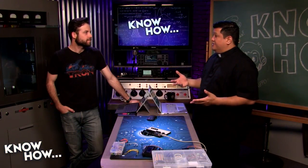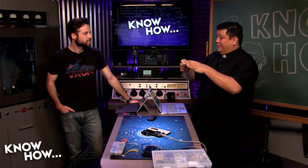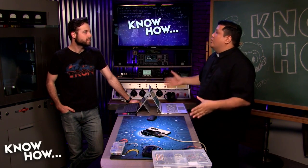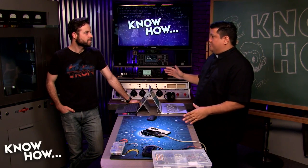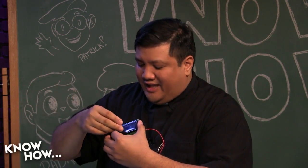They get washed out a bit easier because you have that Organic Light Emitting Diode that's actually competing with the sunlight. There's no way it's going to win. The sun's so much brighter. But with a standard LCD, some of that sunlight actually reflects off the back. And so even outdoors, you can still kind of see it because as it gets brighter, that reflection will get brighter.